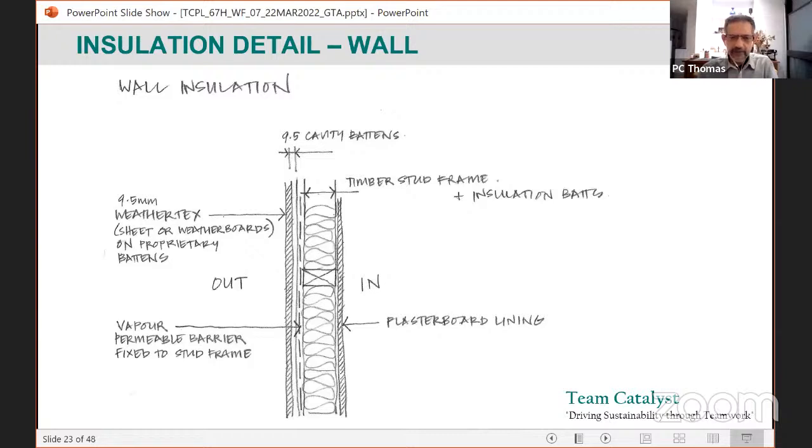You can represent that in Design Builder. So I've got 4 layers here for the wall. There's the weatherboard, air gap, insulation, gypsum, or internal plasterboard. Now, interestingly, if you notice, in this insulation layer, I have used this thing called bridging.